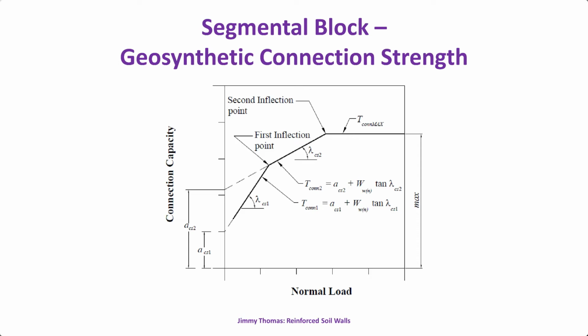So in a wall at each level, I know what my normal load is. From this, I can pick up the connection capacity. That I compare with the connection load, ensuring a factor of safety.